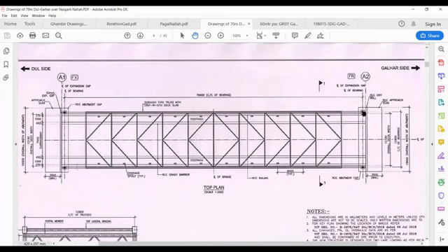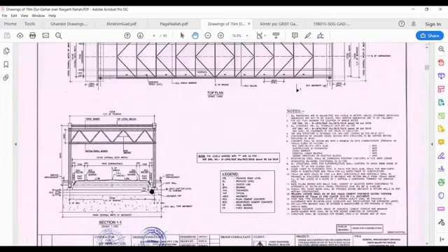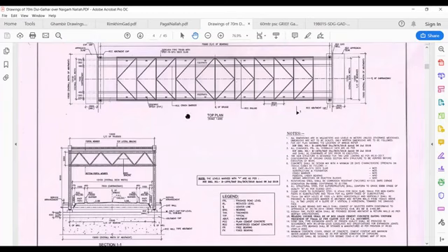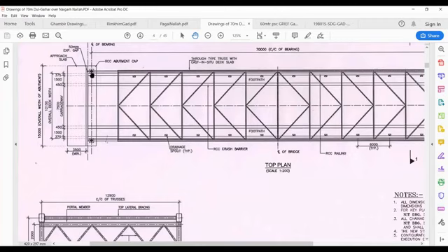But for now, understand that there are 4 bearings in this bridge, which is shown here, and which is also clear. This is one side of the bridge, right? Bridges usually don't have continuous bearings, but if you look at plate girder bridges, then you'll have many bearings. You have like 6 or 8 bearings on one side only.